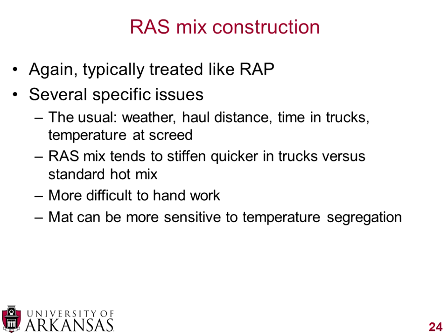Some of the reasons for that is mixtures that contain RAS tend to stiffen more quickly in the trucks versus standard hot mix. That's very similar to why you don't want to keep it in silos. These RAS mixtures could have tendencies to stiffen more quickly than you're used to. Keeping things overnight or keeping them in trucks for extended periods of time could create problems.